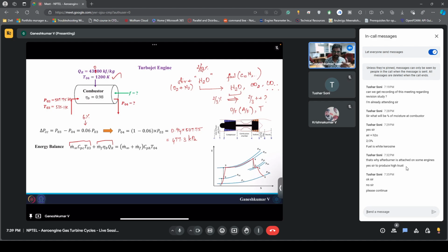The second term is the energy with which the fuel is entering, and which will be equal to the total energy coming out of the combustor. So it's just simple. Energy in is just budgeting. You need to budget the energy. So these two are inlets. This is an outlet. Okay, and you must have noticed that I'm using CPH here.